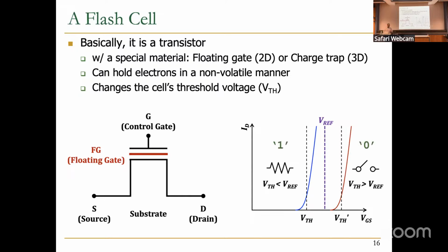So in erase mode, which you didn't program yet, you can encode it as 1, and in the program state, you can encode it as 0. This is called SLC programming, single level cell. But you can also apply several reference voltages and do it more accurately. And then you can, for example, encode 2 bits or 3 bits or 4 bits. State-of-the-art SSDs are actually TLC or QLC, storing 3 to 4 bits per flash cell in order to provide capacity. So that's the programming state and read.